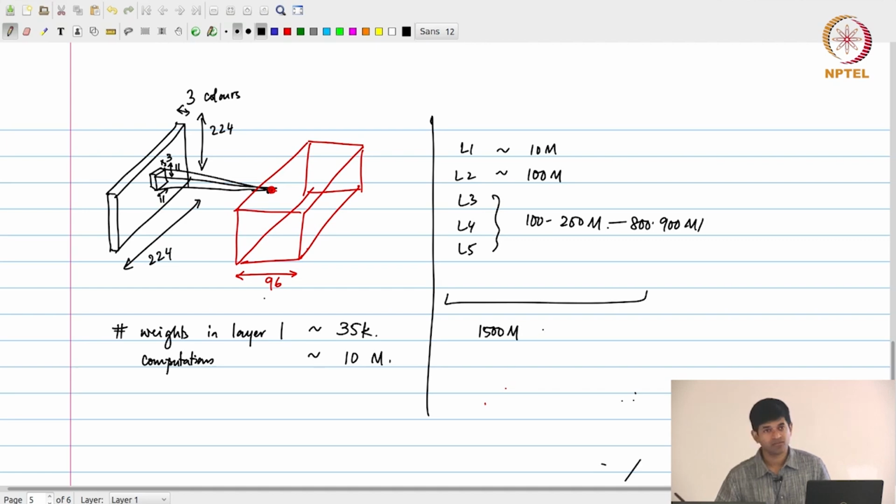1500 million multiply accumulate operations. At least the original AlexNet was just implemented using floating point computation, because they were not very concerned about hardware implementation, they just wanted to demonstrate that the recognition worked. So this is basically the number of floating point operations. Another way of putting it is around 1.5 gigaflops. Note this is just operations, not operations per second, because I don't care about speed yet.